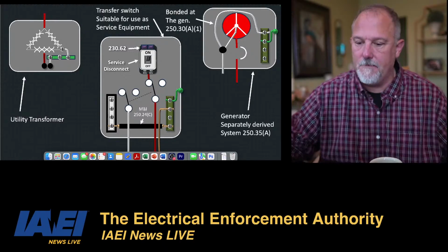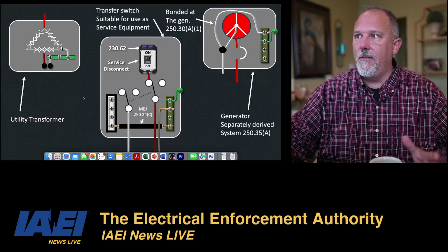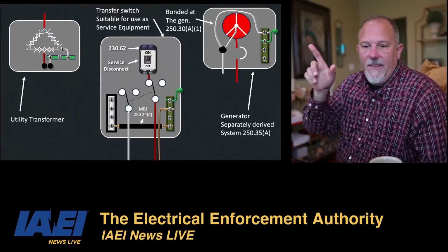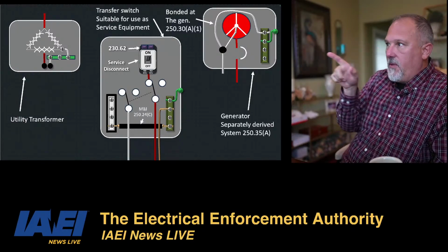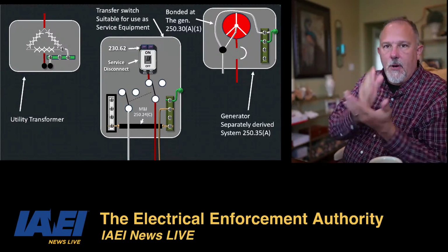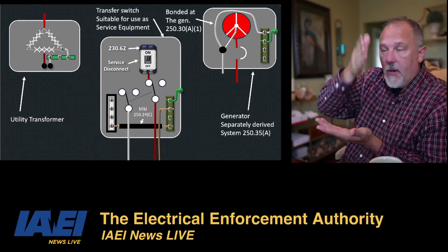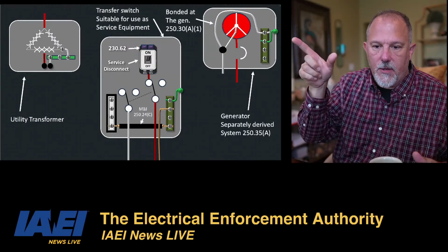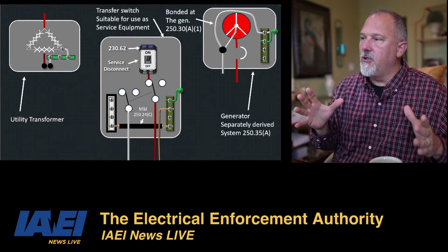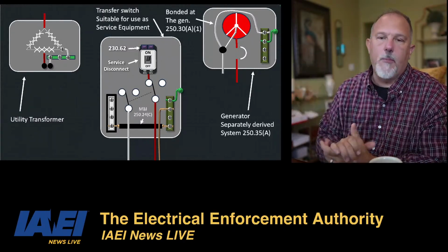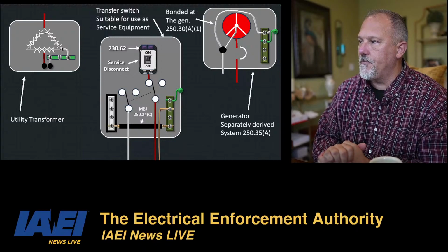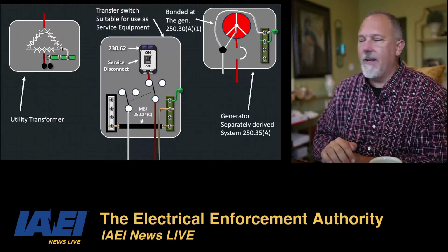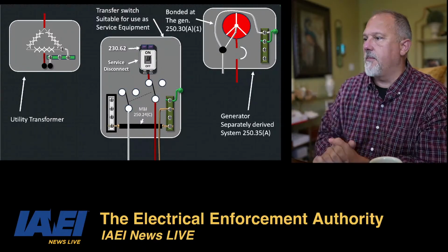Nothing has changed. All right, so now let's just look at this diagram because there's a lot going on right here. Closest to me, I've got a generator that is bonded, where the neutral is to the ground bar inside that, which is bonded to the enclosure, right? So that's what this little green nub is right there. It's bonded to the enclosure. That's all self-contained in the generator. I have a breaker inside that generator as well. That red line represents 3 phases. It just gets too busy if you're going to draw 3 separate lines.